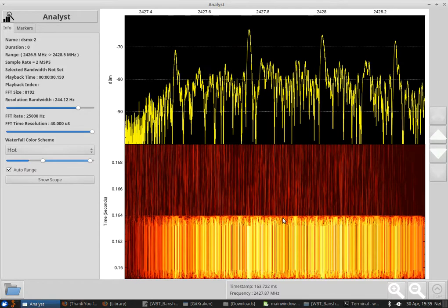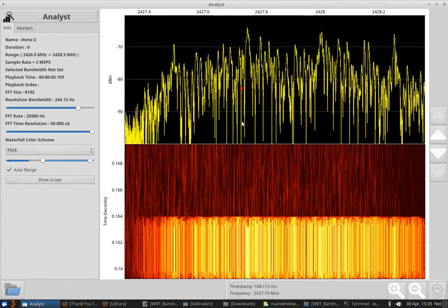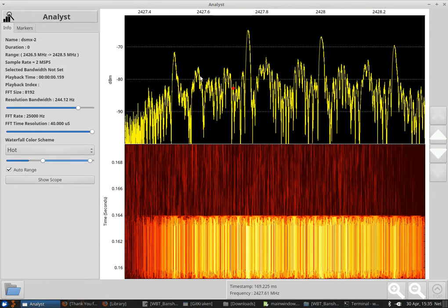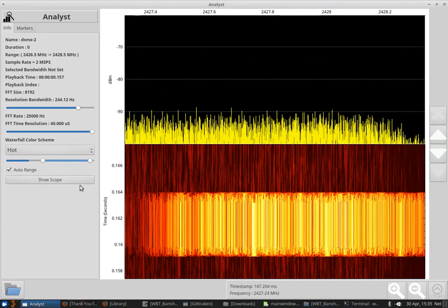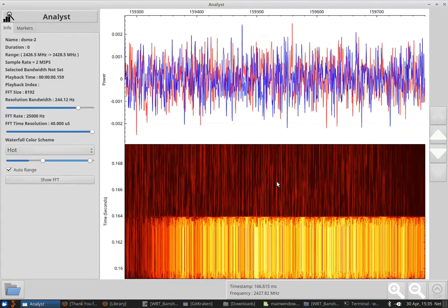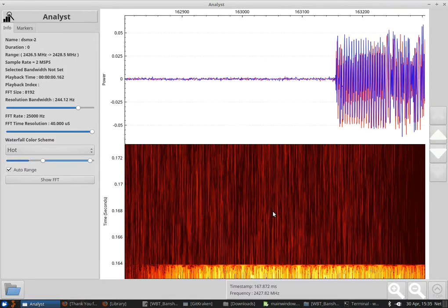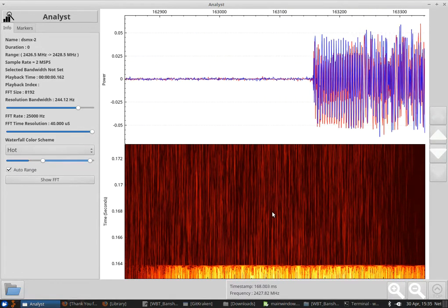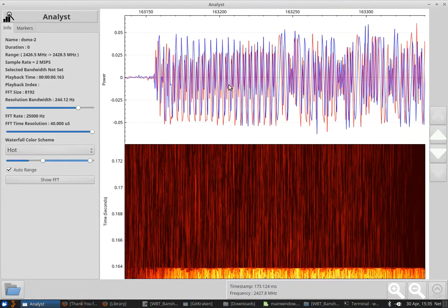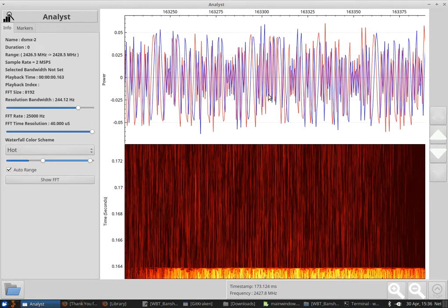As I move across the threshold, you can see some of the characteristic spikes that the decoder would pick up on in order to demodulate this 64-bit block. We can take a look here in time, so you can additionally see what happens when I move across the boundary threshold. You can see the pulse, as well as some of the preamble going on, which follows into the rest of the data stream.